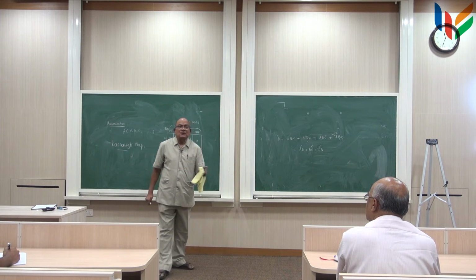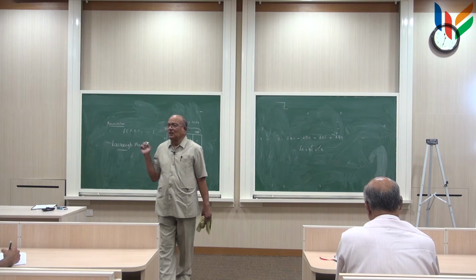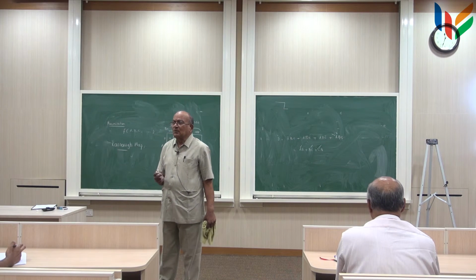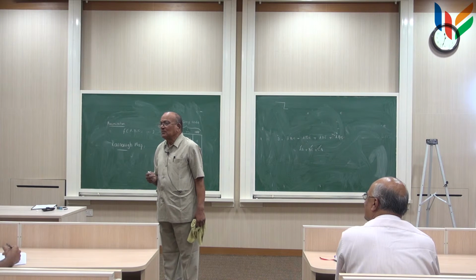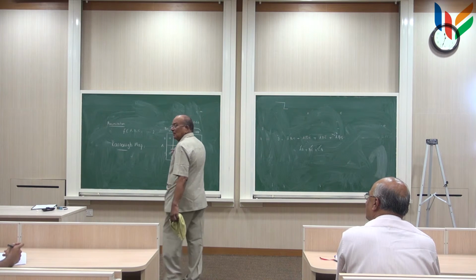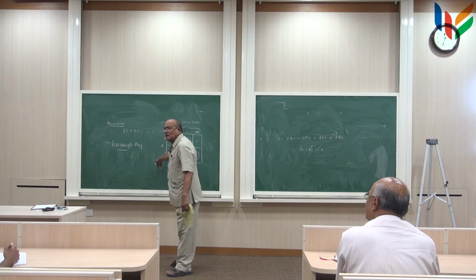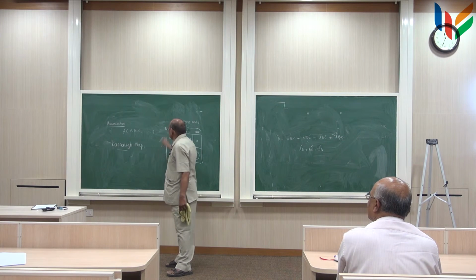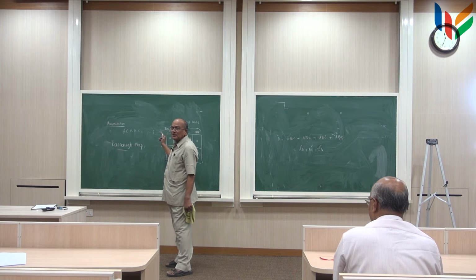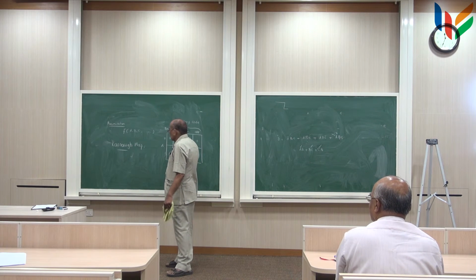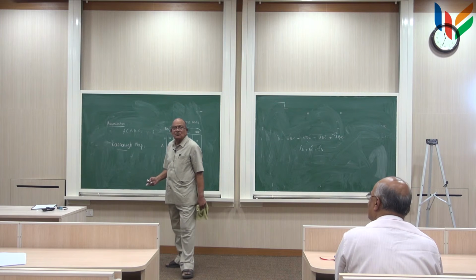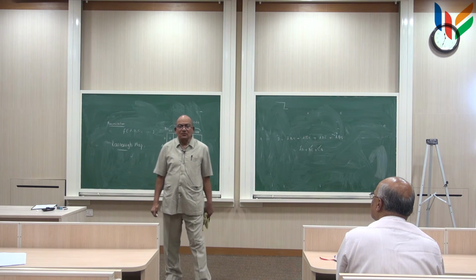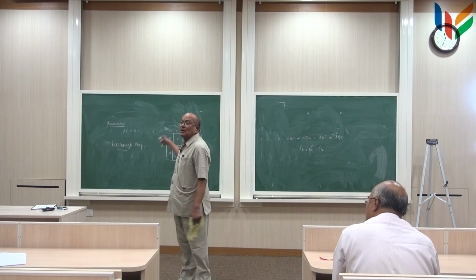So this is the minimization technique, simple minimization for 3 variables. If you have 4 variables, what do you do? Same idea. Here you take 2 variables, here you take 2 variables, but this arrangement of the 2-variable combination must again be a Gray code variation, and then put your functional value corresponding to the Boolean variables, and then try to look for neighbors.